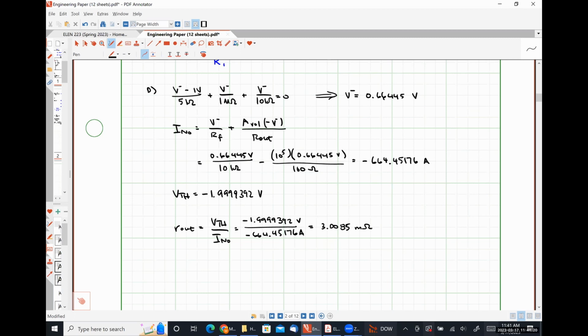In fact, at some point, I'm just going to have to update this to be a non-inverting amplifier, and then you would see that the input resistance would be really close to infinity or much larger than Rn, but I keep forgetting about it until I get to this point and realize I could have done this better.